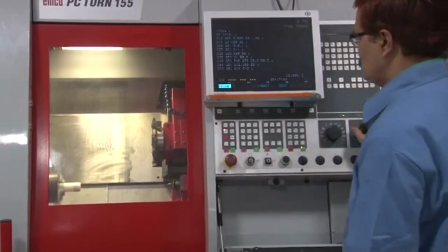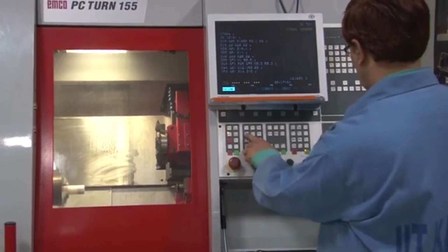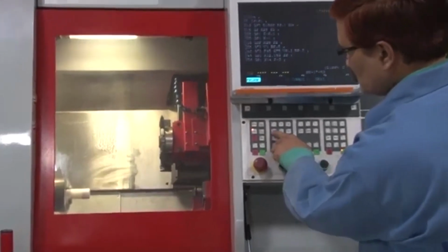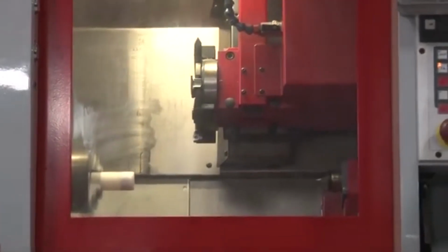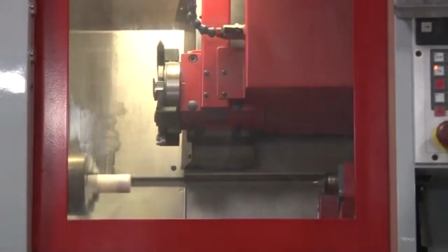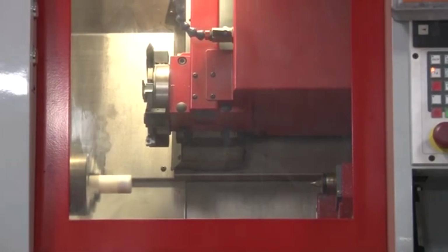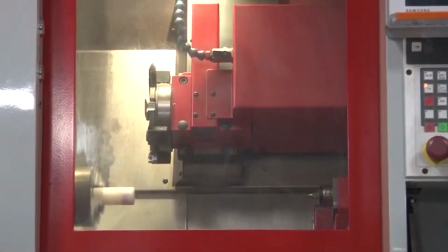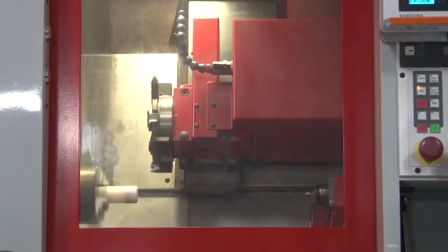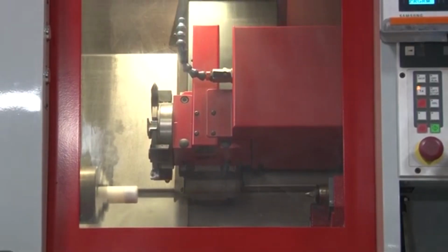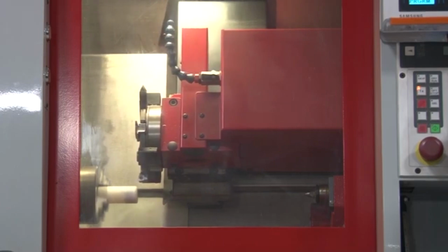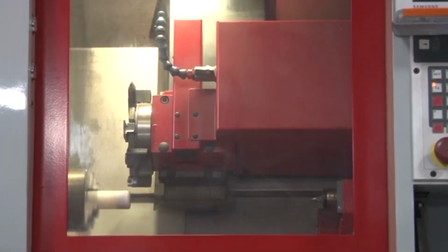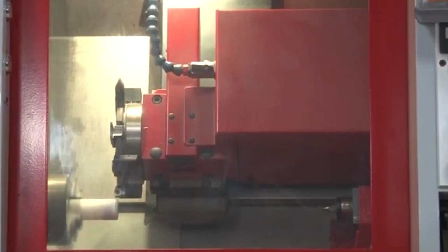The workpiece started rotating, and in the jog mode you can see in the display, we are bringing the tool to the 0 position, so that it can start the machining process from that point. This is the x direction. Prior to that it was moved in the z direction. Those coordinates are already given in the program. According to that program it will be moved.